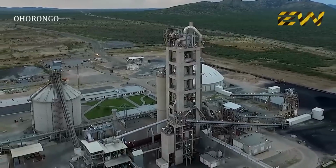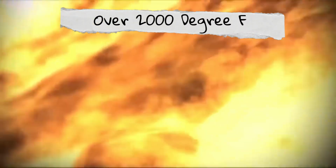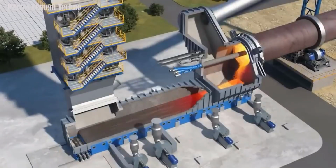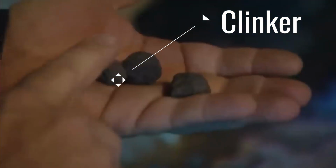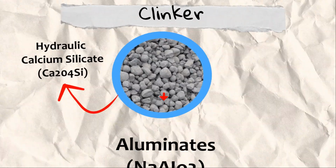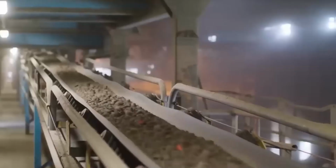Fuel is burned at the lower end of the kiln to generate immense heat reaching over 2,600 degrees Fahrenheit. This extreme temperature kicks the chemical reactions and clinker formation into high gear. As the raw meal slides down the kiln, it forms condensed minerals called clinker. Clinker consists primarily of hydraulic calcium silicates, aluminates, and aluminoferrates. These hard granules form the active ingredient that confers cement its binding properties.